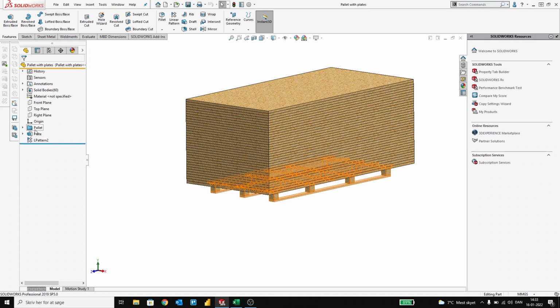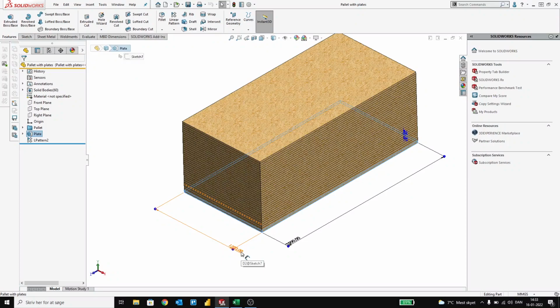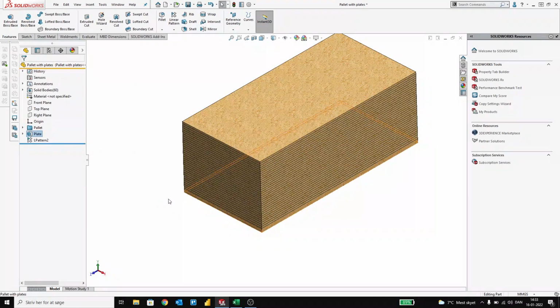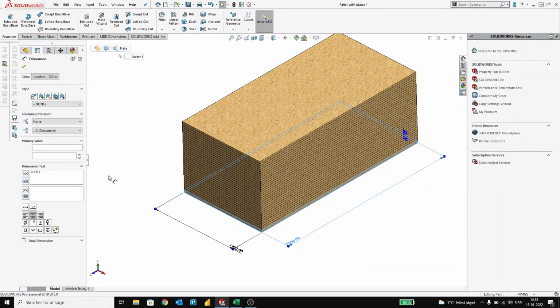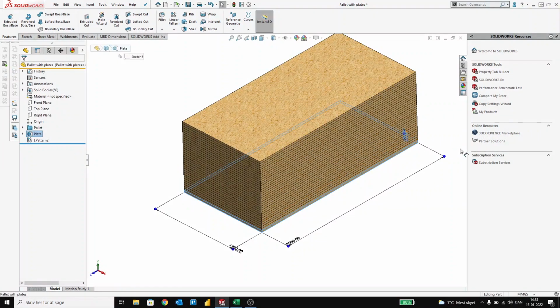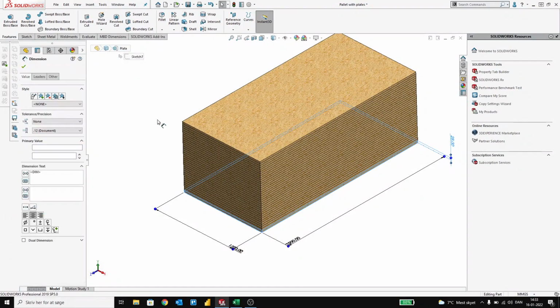So the very first thing that I would recommend you to do is to name the different dimensions that you have, so that it becomes a lot easier for you to identify which different dimensions are what in your design table. So what you should do here is to open up the different dimensions and call this, for instance, the width. And over here we have the length of the plates. We do also have the thickness over here that we would like to define as well.